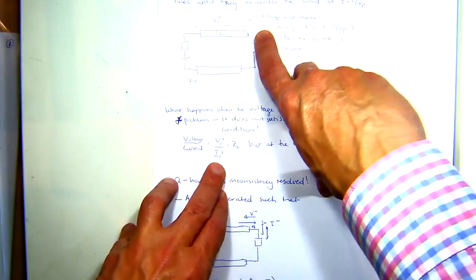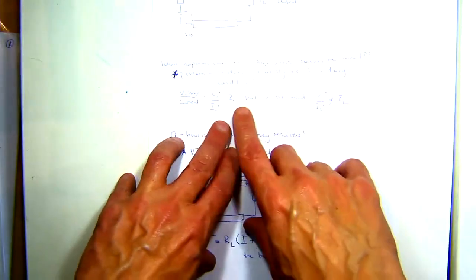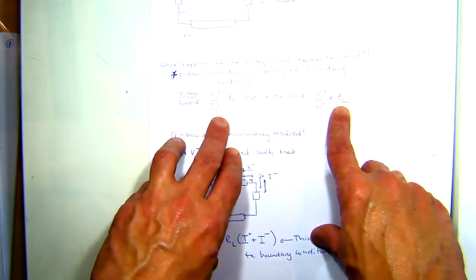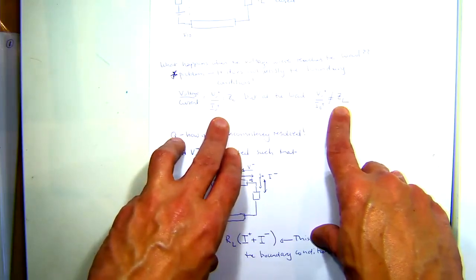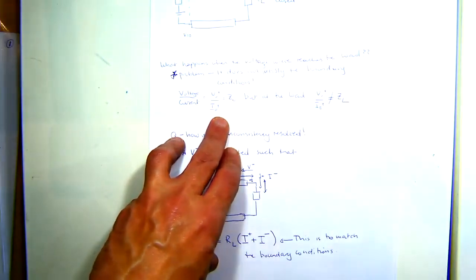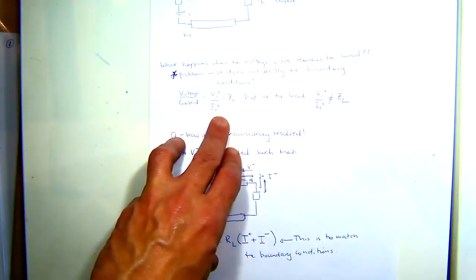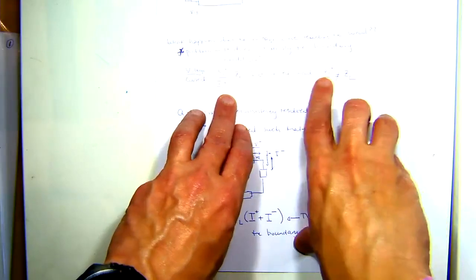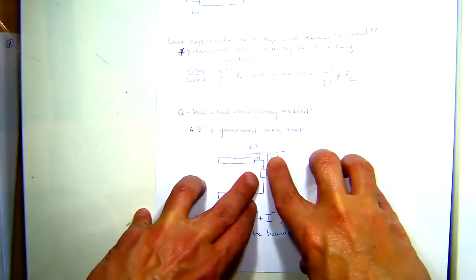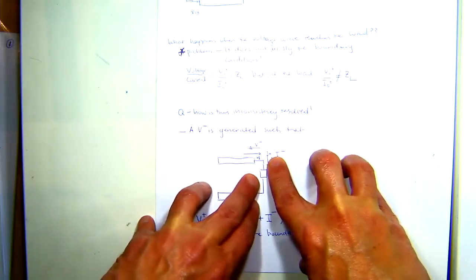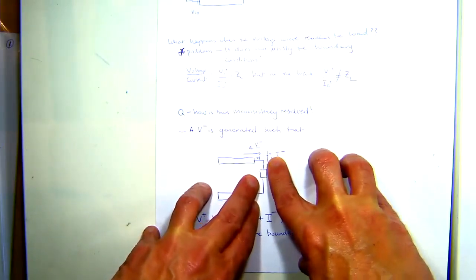When it hits the load, all of a sudden the wave realises that it doesn't meet the boundary condition, that the physics isn't being met. So in order for the physics and Ohm's law to be met, there has to be a reflected wave at that particular location in order to meet those boundary conditions.